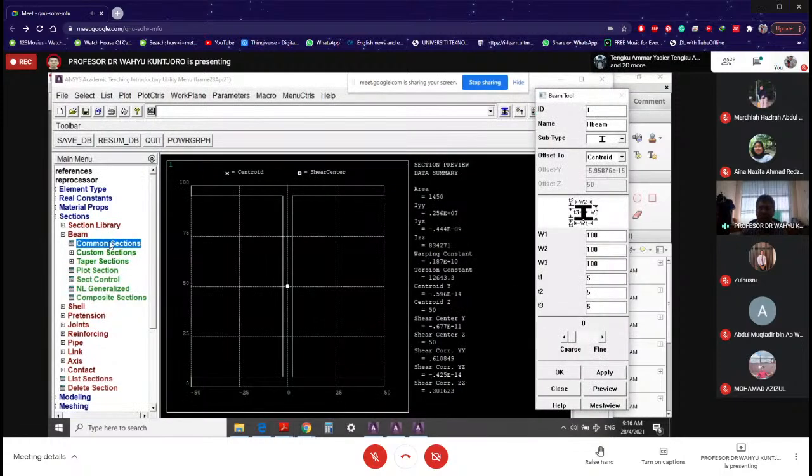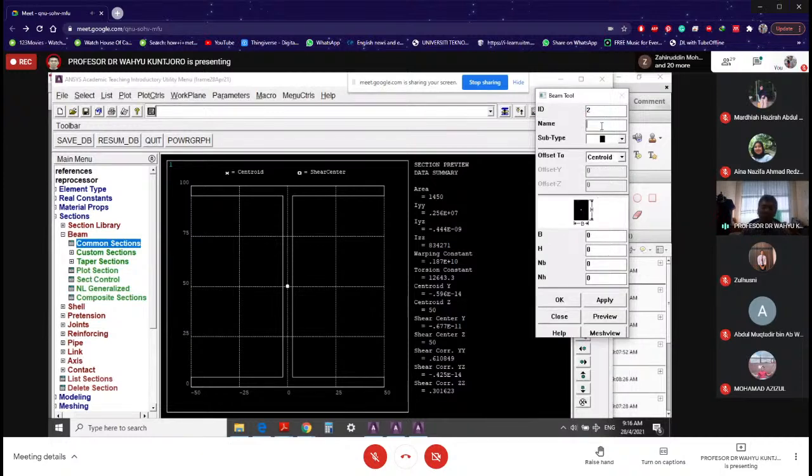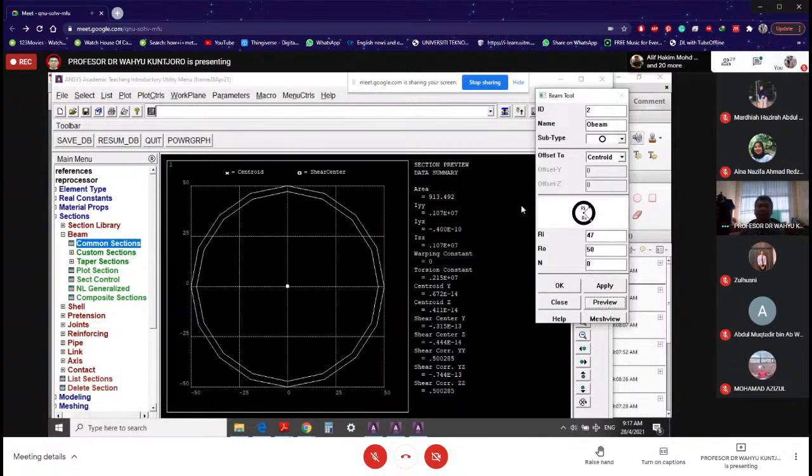So I click common section again. ID is now becoming number 2, don't forget. And I'm going to name it that way, OBIN. And that's what we want. Okay, inner radius, 47. Outer radius, 50. All right, so if you click apply, then it is going to be there. Let's preview. So that's what we have. Inclusive with this is our information on the properties of the section.